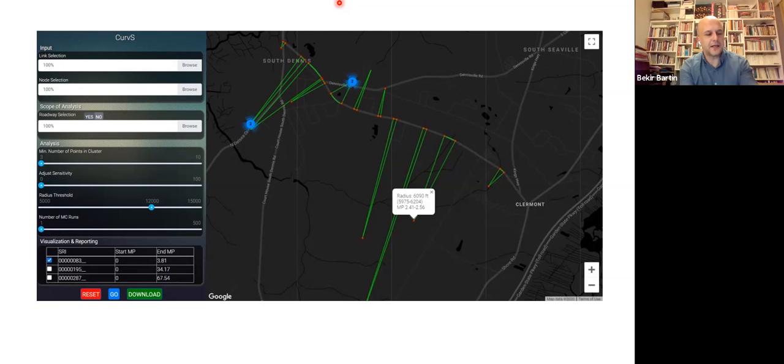Yeah, that is exactly what I was referring to in the Highway Safety Manual. The reason why the alignment data, or to be specific, the radius and the curve length, is required is because you would like to find out what the crash modification factor related to curves is. Meaning, for instance, if the predictive function gives you X number of crashes per year for a tangent section, what happens if that section is not tangent but is a curved section with a certain radius and length?